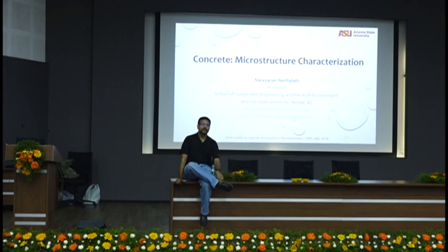Good question. When you cut, the microstructure can be disturbed. But what you do is, if you're doing backscatter, microstructure disturbed meaning you might form some additional cracks. That's pretty much it, if you don't cut carefully. But if you really carefully cut with the appropriate tools that they have to cut, there won't be significant changes. There's some slight changes, and then if you polish it for backscattering, you will mask those changes. Generally, you won't find that many changes.